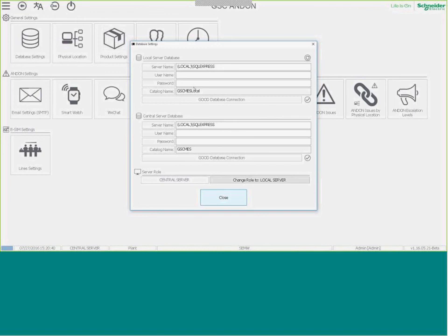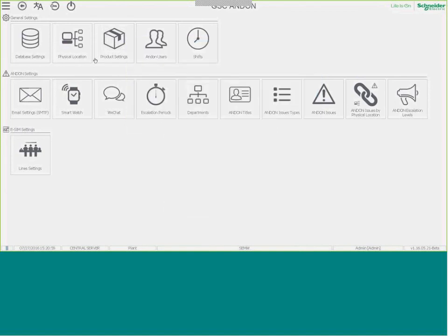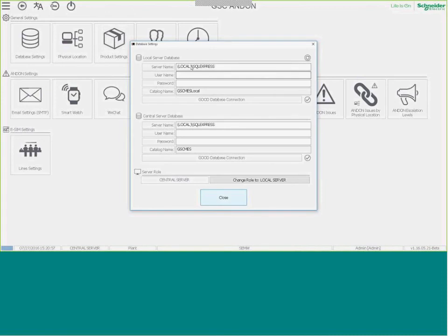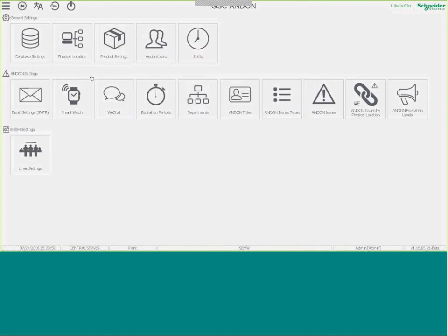And you do not have to manually create the tables or the columns. Once you point to the database and click on this button, InduSoft automatically creates the database, creates the tables, everything automatically. You don't have to do any database configuration manually. Just point to the server where the database is running.